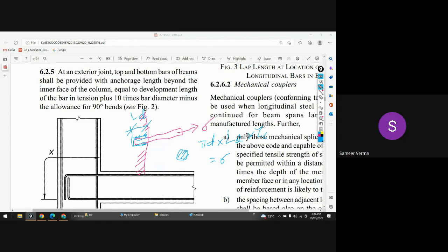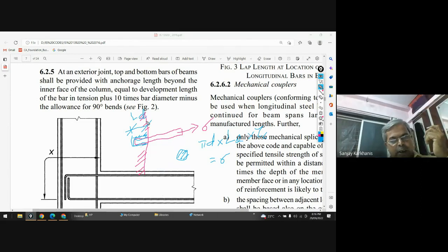That's why you need Ld, because once you have defined the diameter of the bar, you cannot change it. This is constant. Then there is the stress that concrete can have, and as the grade of concrete increases, the frictional stress of the concrete also increases, and you can get it from your books or codal information. It is something around 2.5 for M25, or the maximum is something around 3.8 Newton per mm square.